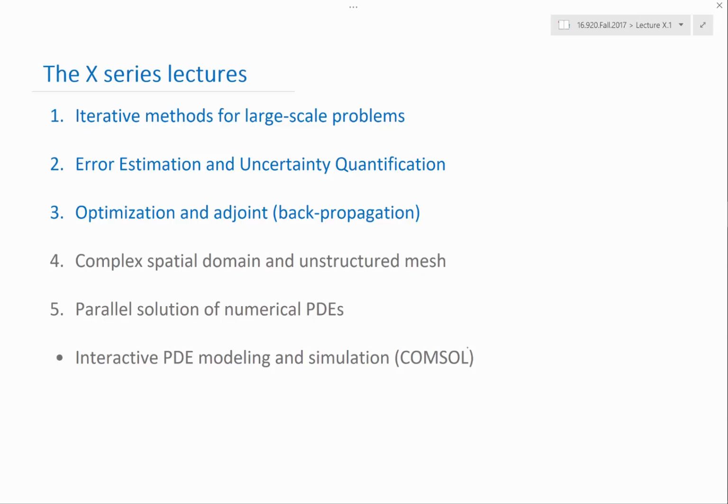Traditionally, the method of quantifying how much error is due to the numerical methods is usually called error estimation. But there are also errors due to other things, like the geometry. You may not get the perfect domain corresponding one-to-one to what is physical. If you're solving structural problems, you may not have exactly the right material properties.